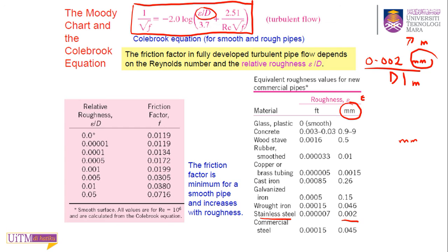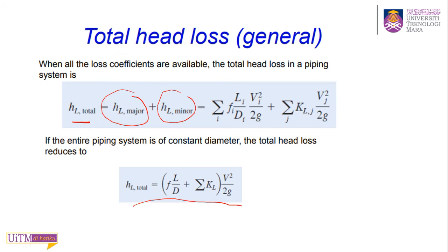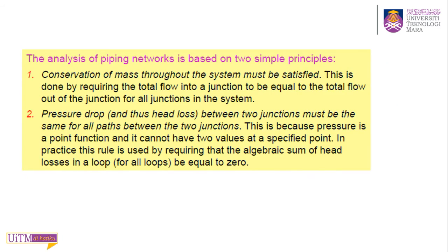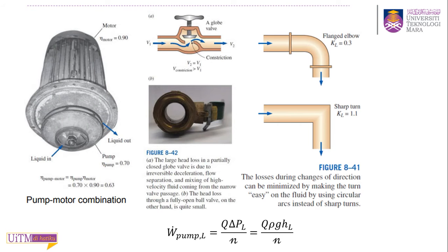But in reality, sometimes if they provide you with that efficiency, we need to divide that equation with the efficiency. So this will give you the total pumping requirement, how many watts the pump will give, if the pump has 70% efficiency or 80% efficiency, you need to divide by that efficiency.